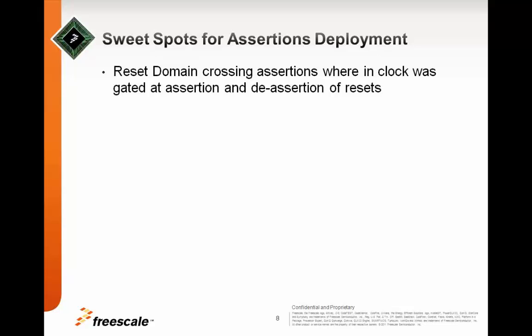Moreover, in a low power design where clock gating schemes are employed to save power, the clock may be disabled accompanied with the assertion of reset. Thus, in this case, only an asynchronous reset will work. Thus, in our SoC design, it was ensured that the system clocks were gated during the reset period. It is critical to check this design behavior across all the resets in the system, and we were able to successfully deploy the low power assertions, check the reset domain crossing behavior, and resolve all the crossing issues which can be present.